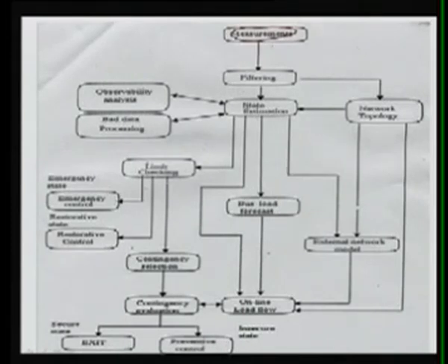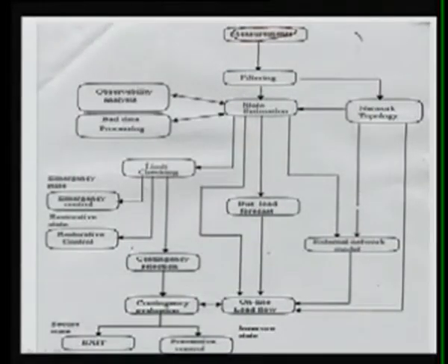These measured data normally will have bad data. Bad data may be of two types. Some data you can directly say, by looking at the information, is wrong. For example, suppose you are measuring a bus voltage at some point and it is 2 per unit. This shows that, while your power system is running, it is not possible that your voltage magnitude is 2 per unit. Similarly, you can see another example.